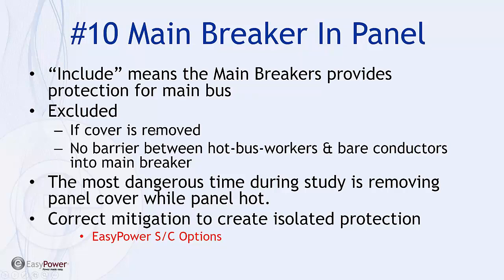Very often the most dangerous time of any procedure is when you have to remove the cover, and for some reason you're not prepared to carry the load, or the load shifts because of the extra weight. Having that cover fall into the electrified panel is very dangerous, and the potential to create a short upstream on the main breaker is real, and that's just one example. So consequently, if there's a short that's created there, is a person protected downstream by that breaker? And the answer is no.